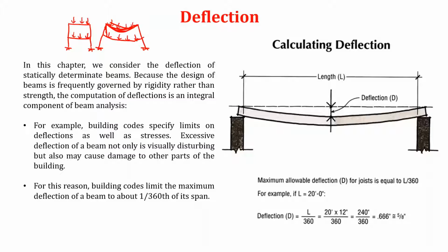That's why, in design, sa structure, we also have to take note or consider the maximum allowable deflection. Okay? So, that is in our code. So, for a beam, the allowable lang na deflection or highest na pagbaba niya diri must equal to the total length divided by 360.